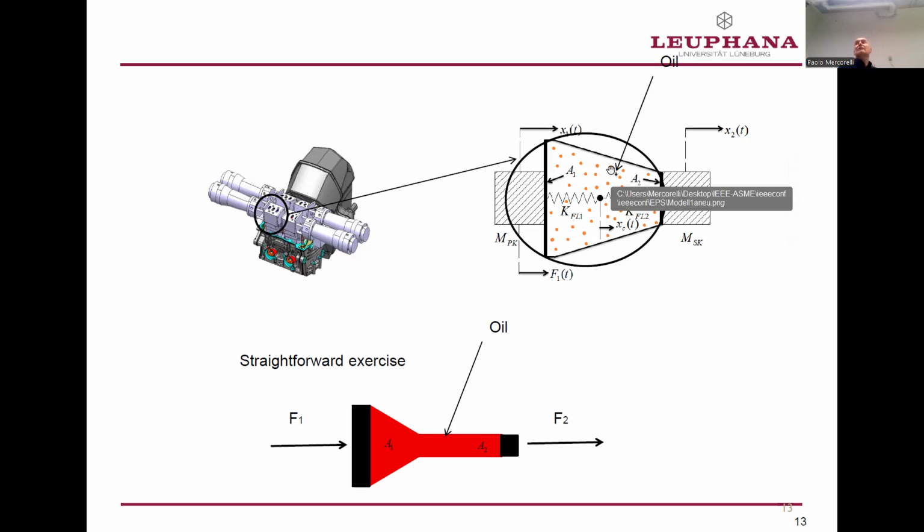And the model of this ratio, this ratio or gear is not exactly a gear in the specific term, can be realized with hypothesis of compressibility. The hypothesis of compressibility is more general. This means we can model here with a spring and damping, not only with a spring. I don't know why the student didn't put also the damping factor. But could be done, as in our case here in the lecture, considering not compressible, compressible fluid here inside.